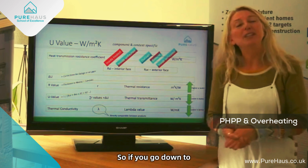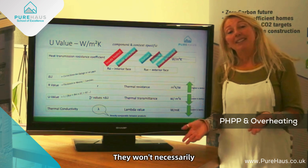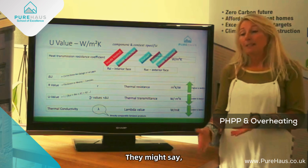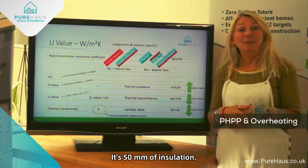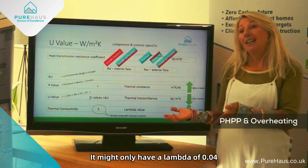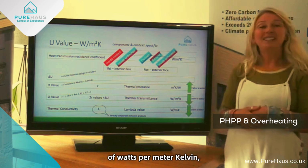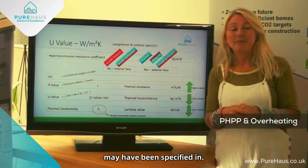So if you go down to the builder's merchant and say, could I have some insulation, they won't necessarily have appreciated the lambda value. It would be wrong to say they don't understand. So they might say, we haven't got any of that in stock today, but we can give you this one instead. Say you want 50 mil, I've got 50 mil. It might only have a lambda of 0.04 as opposed to 0.036. I know that's only 0.04 watts per meter Kelvin, but I promise you it would make a massive difference over the surface area that may have been specified.